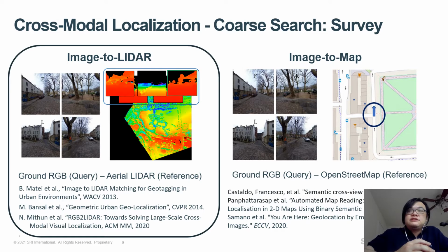The LiDAR sensor is typically more expensive and also bigger than a camera. However, it can get accurate 3D information of the scanned environment. So it can build a 3D point cloud of the target environment to create a 3D geo-referenced database for accurate localization applications.